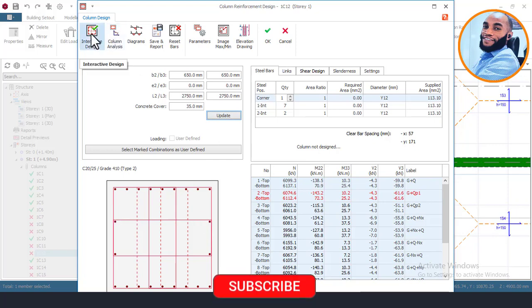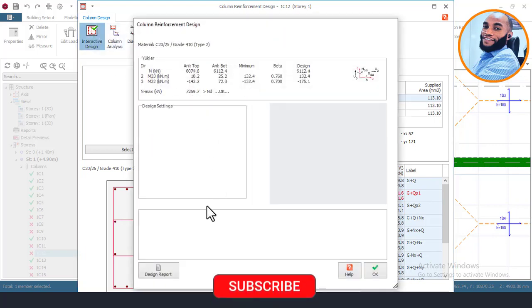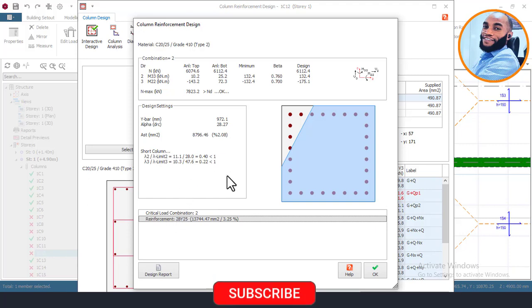And I'm now coming right now and then click on the interactive design here, and I'll wait for the column to show again. Now, once you are able to see your column, if it's perfectly okay, you will not see any warning in here. What you will see is the reinforcement. So once you're able to see the size of the reinforcement, then it knows that that column is okay and is good.